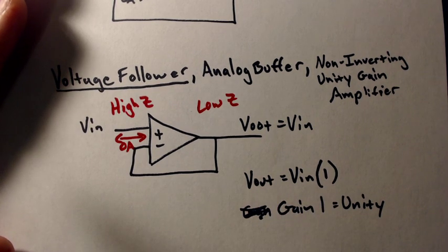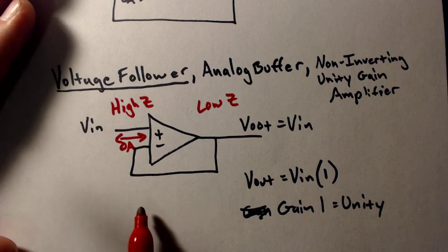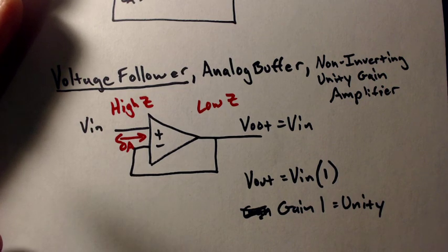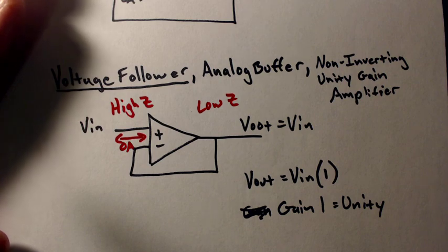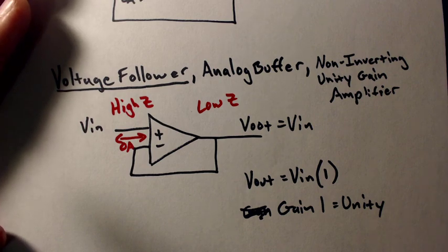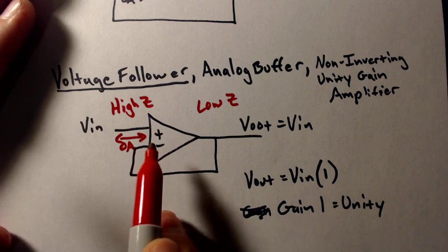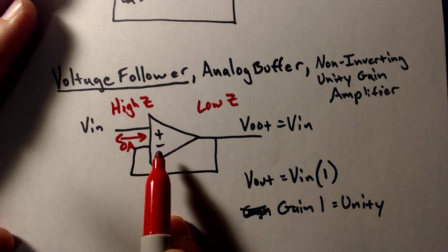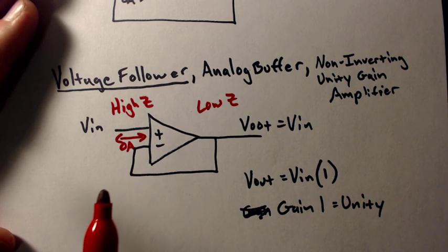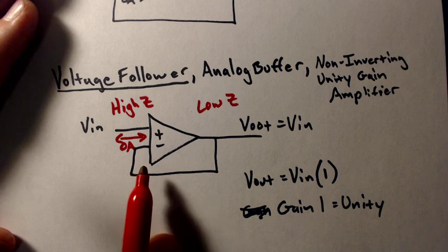So remember that with that common emitter amplifier, between the source and the input to the amplifier, you created this voltage divider situation. Well, this lets us get rid of that problem. We don't have to even calculate the voltage divider, right?